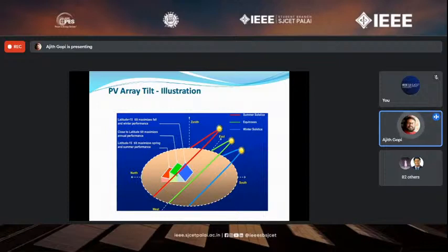So in Charanka Park, we did a tilt of 37 degree during the period of October to February, during the winter period. So that was an adjustment of 22 plus 15. As a thumb rule, you look at this slide.